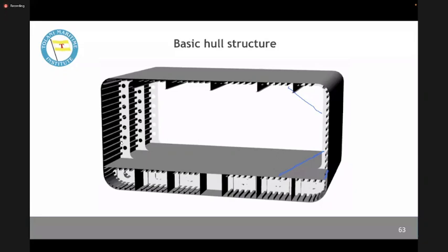It is going to be difficult, because when it is an oil tanker, you are just pumping out, so you don't require anything. But for solid cargo like this, you cannot. It is difficult to get these cargo items, and you are not going to send a person with a broomstick to clean it up. Mostly it is done with the help of mechanical grabs or some machines which will go and scrape off all the cargo. If you don't have this plate, then it is very likely that the ship is not a bulk carrier. Because when you are making a ship, you have to think of what type of cargo you are taking.